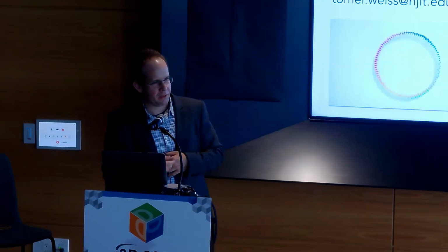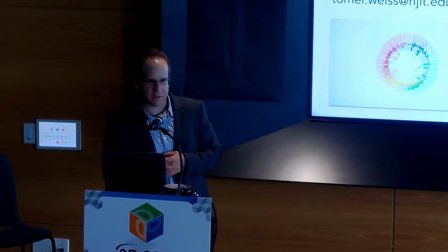Thanks. You said you were using a Jacobi solver for your constraint. I assume your stiffness constraints are symmetric between the two agents. Correct. So would it be possible to use a conjugate gradient instead? Well, yes. We didn't try that, but there's work on how to use PBD with conjugate gradients. There's a SIGGRAPH paper, I think by Yuming Wang from Ohio State. We didn't do that, but that's subject to future work. All right, thank you.